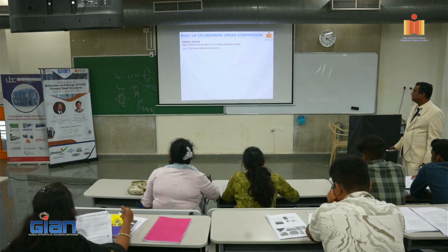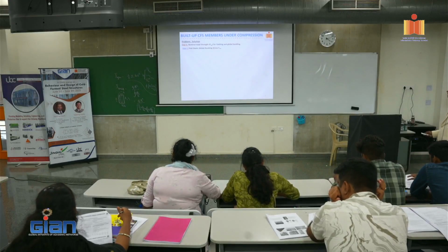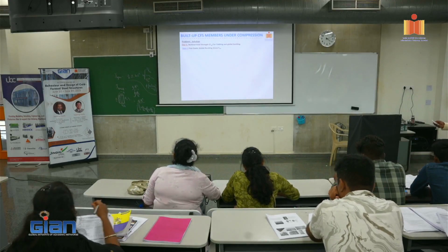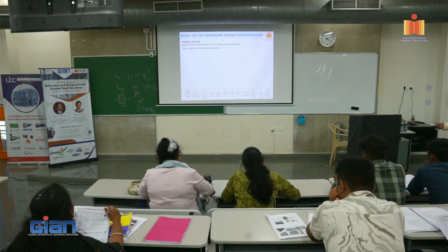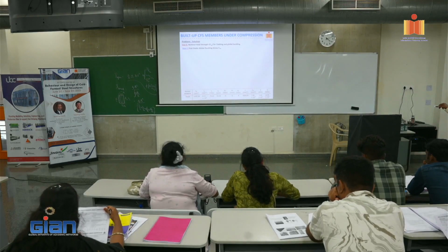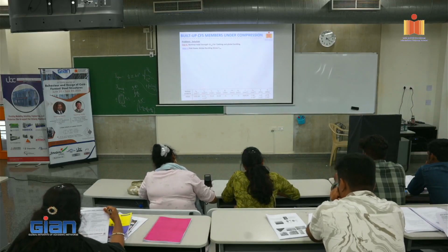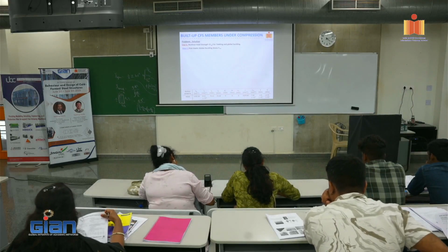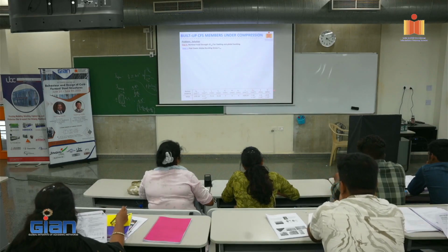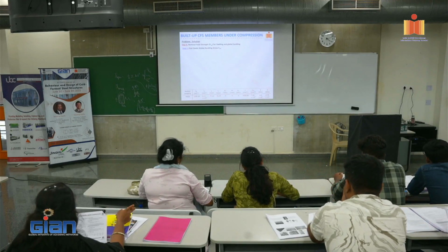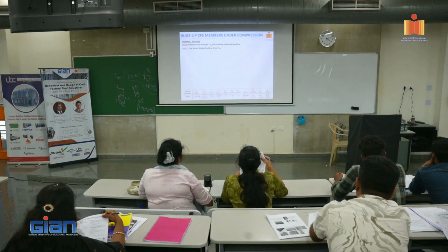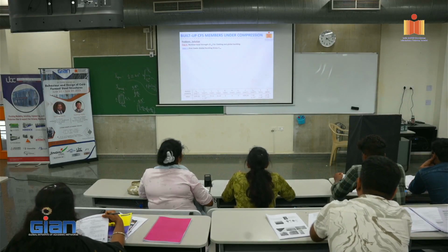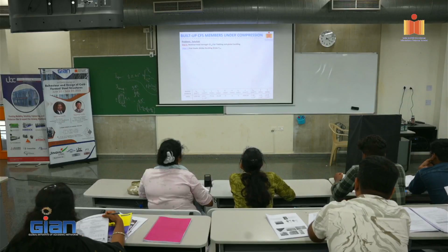So let's look at it. The nominal axial strength Pne for yielding and global buckling, right? So find elastic critical buckling stress, that is our objective. We have put all the properties that we have calculated here, Ag, Ix, Rx, Ry, xc bar, m, X0, J, Cw, E and G, right? All these section properties, including the metal properties, are here. Step 1, our objective is to find out Fcre. But our major objective is to find out Pne.